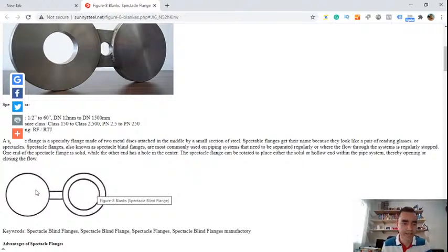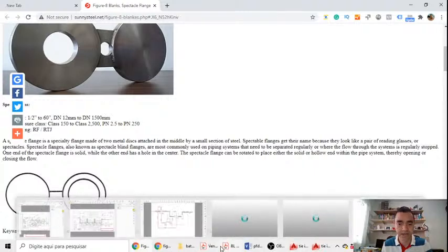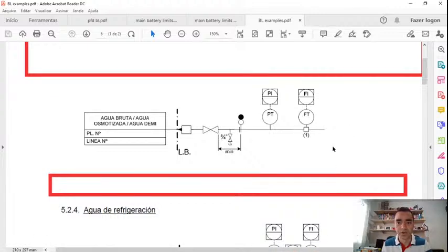If I shift this or if I rotate this in my pipeline, I isolate the pipeline and I am not able to feed anything to my process, and with that we guarantee that the process is isolated from any kind of fluid.